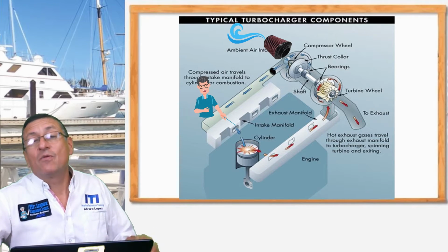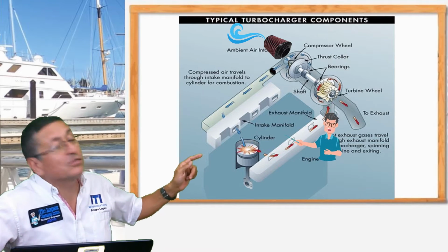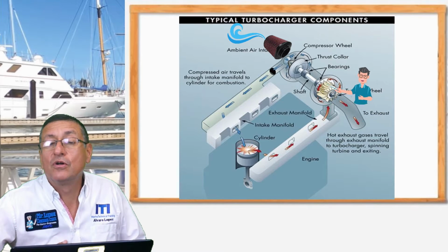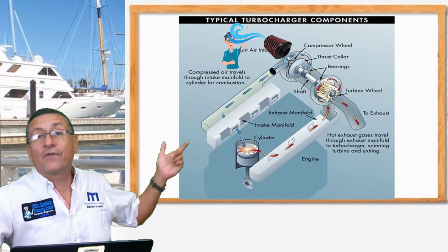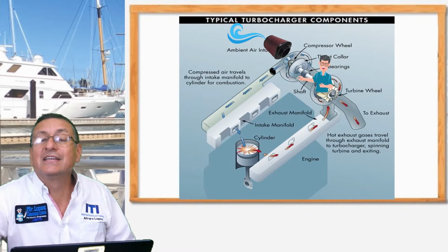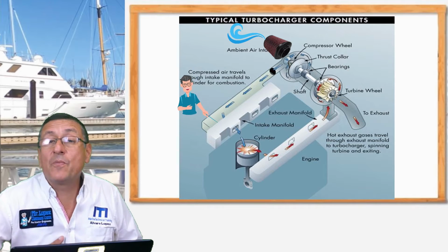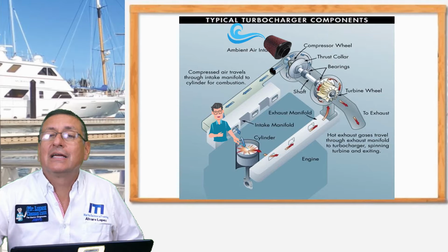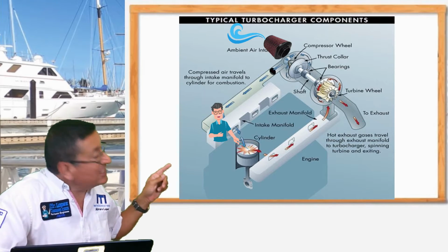And once again, when the piston goes up with the exhaust valve open, the exhaust gases go through the exhaust manifold, spin the turbine of the turbo in the hot side of the turbo, the excess of gases goes out, in the other side the fresh air enters, the fresh air is compressed, and enters the intake manifold highly compressed, and enters again in the combustion chamber. I want that you check one engine with turbo and check that situation.